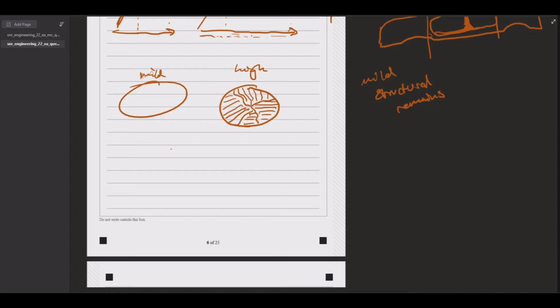That's going to be an intimate lamellar mixture of ferrite and cementite, where it's going to be one phase though, so it's just pearlite really. And that's going to give us a very strong material. So the brittle stiff material combined with the soft, very ductile ferrite is going to give us a decently stiff, but also malleable stress versus strain graph.